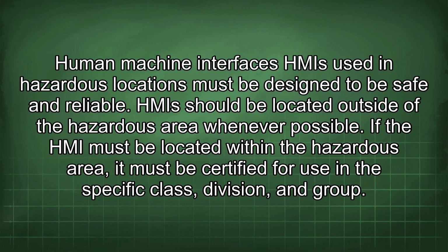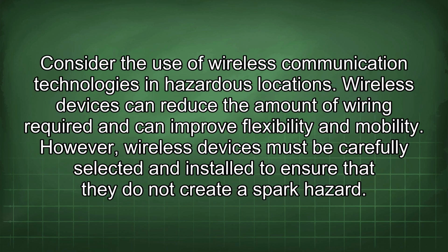Human-machine interfaces (HMI) used in hazardous locations must be designed to be safe and reliable. HMI should be located outside of the hazardous area whenever possible. If the HMI must be located within the hazardous area, it must be certified for use in the specific class, division, and group.